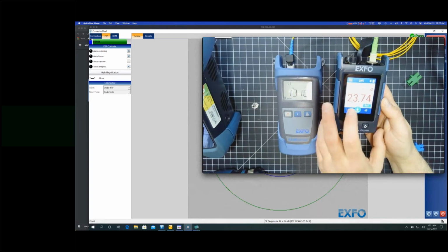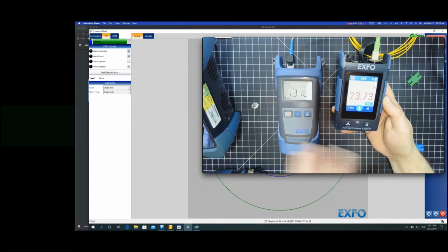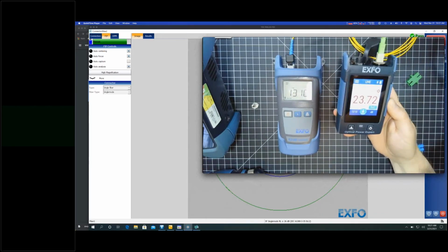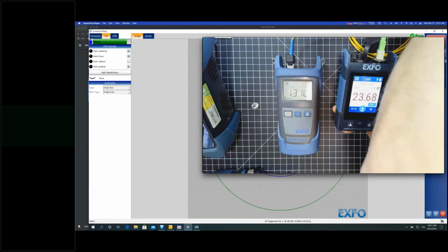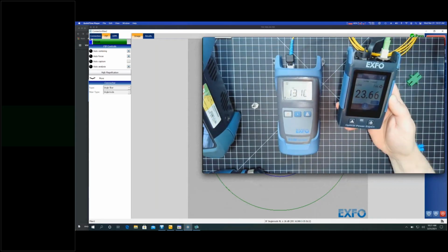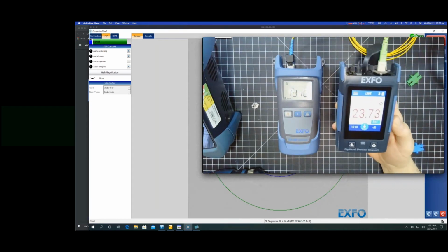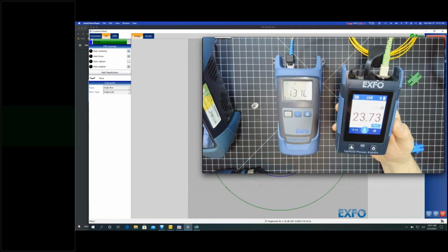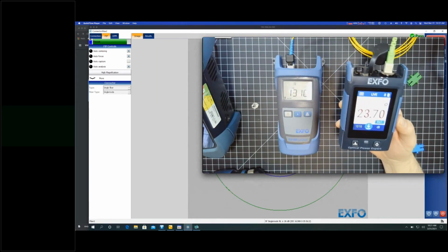But like I said, I wanted to make sure that we understood the reference method, because I'm using a couple different connector types. I see that question coming up often in the field: how do I connect everything? Now, one of the key components to using that 3-cable method is that I'm actually calculating the loss of those connectors.